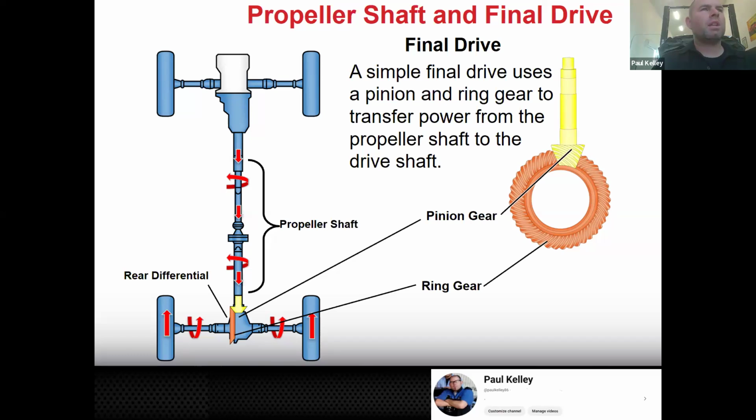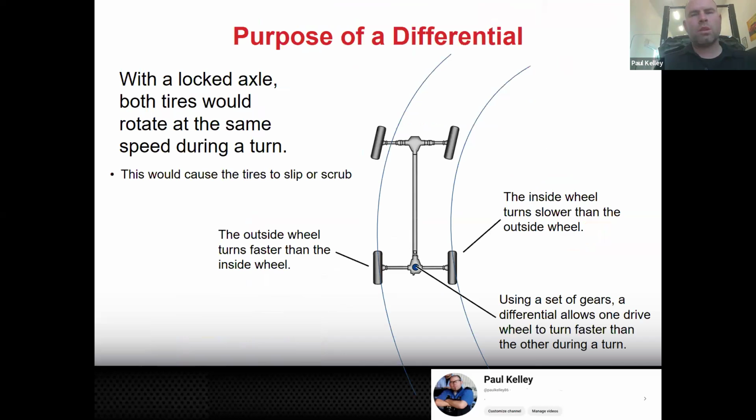And there's a lot of different types, right? But either way, they're going to have differentials. There will be a rear differential. If it's a four wheel drive, there will be a front differential, and those have to be geared the same. They have to be. And then when we get further in, there's even the center diff, and I do cover that just a little bit. So we can have 3 differentials in some of the more high end, like a full time four wheel drive. Cool. Now let's summarize what you did in that discussion.